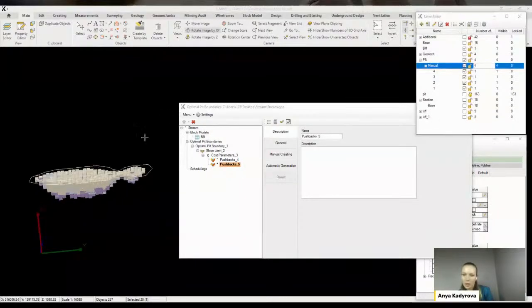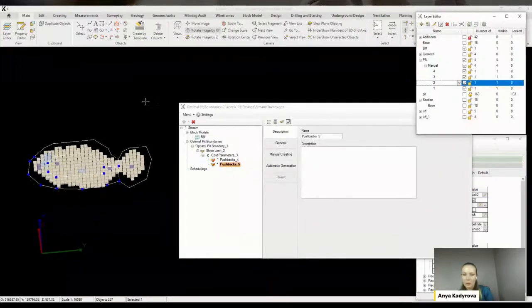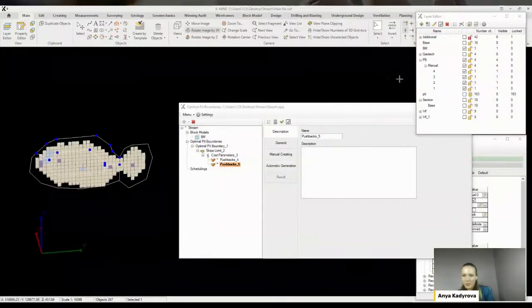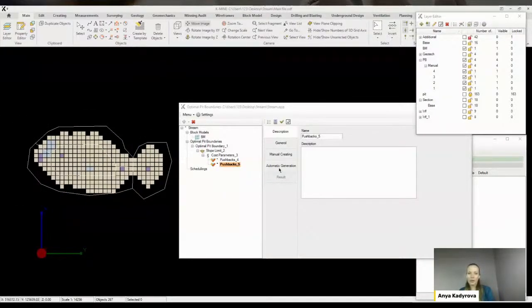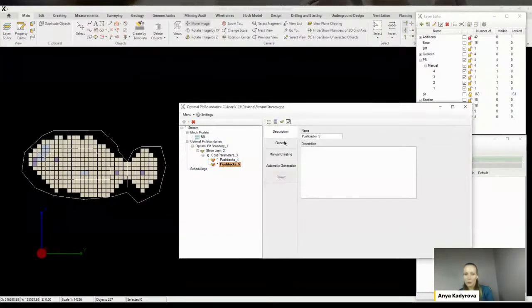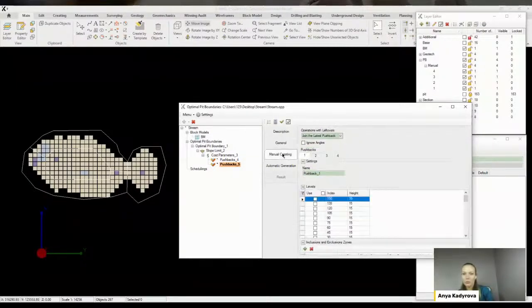It's 4 contours that were previously created, conventionally the center of the pit, south, north, and a separate part east. Let's specify similar parameters for manual construction. If the blocks are not defined in any of the pushbacks, they will be included in the separate one, which is indicated in the parameters. And we will not use height restrictions. We will only indicate the layer in which each of the restrictions will be stored for each individual pushback.